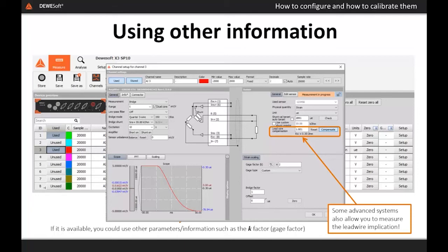An important aspect of this function is that it is primarily intended for the calibration step, as any variance in lead wire resistance can be accommodated to a large degree by taking advantage of sense lines where they're available. Notice the offset indication that was visible previously. Oftentimes this is something that is required as a comparison to the balanced value.